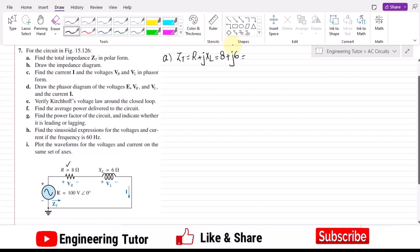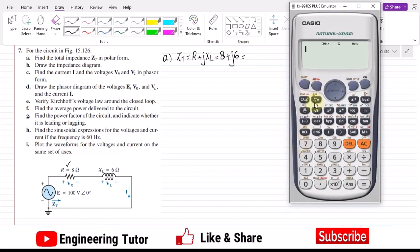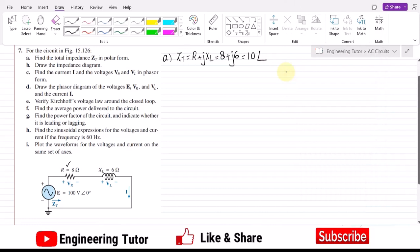Now in order to convert it into polar form, let me use the calculator, and here 8 plus 6i. Converting it into polar form, it will be 10, and the angle it has is 36.87 degrees, and that is basically in ohms.